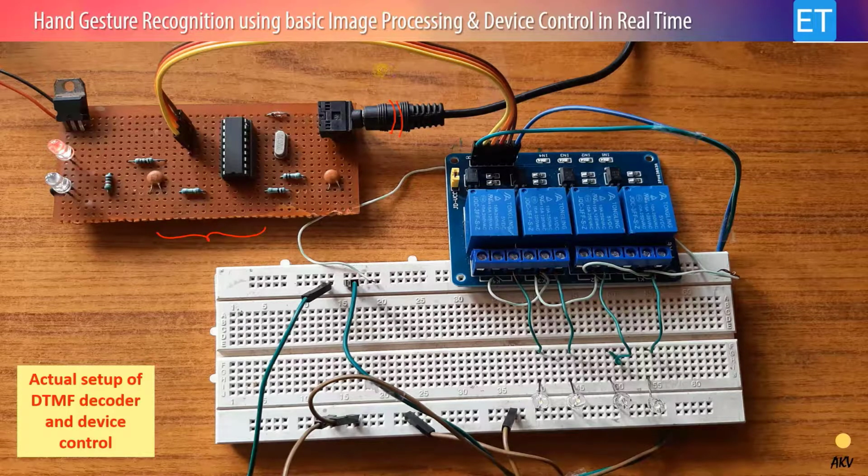So suppose the number of fingers identified is 2, then the binary equivalent 0010 will be generated by these 4 lines. These 4 lines are going here, and this is your relay driver circuit. So here you can see the 4 relays and associated hardware, and here I have connected 4 LEDs as the load, LED 1, 2, 3 and 4. When the fingers are identified, the corresponding binary code is generated, and then relays are actuated according to that. So your corresponding LEDs will be on or off.